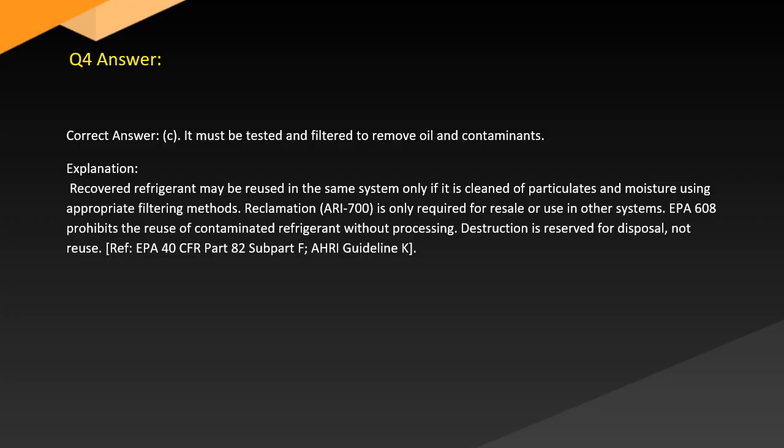EPA 608 prohibits the reuse of contaminated refrigerant without processing. Destruction is reserved for disposal, not reuse. Ref: EPA 40 CFR Part 82 Subpart F. Refrigerant Guideline K.